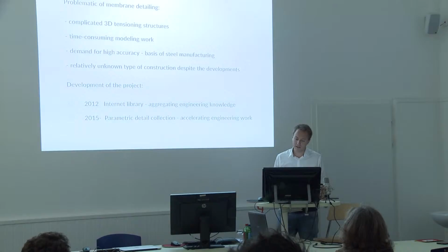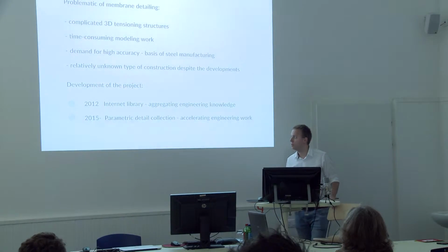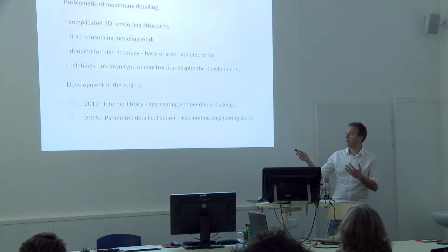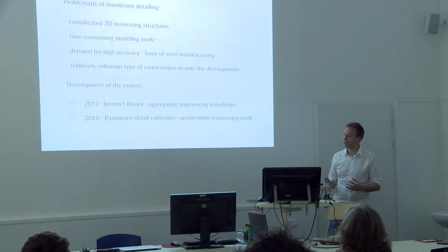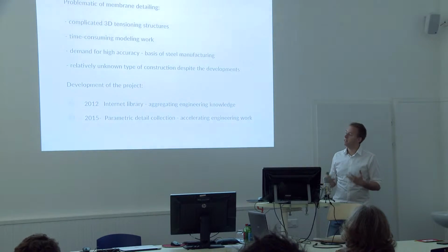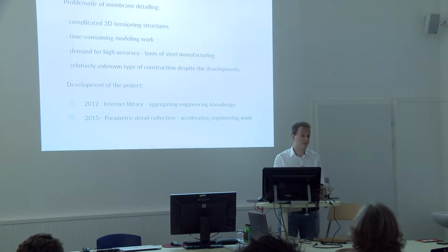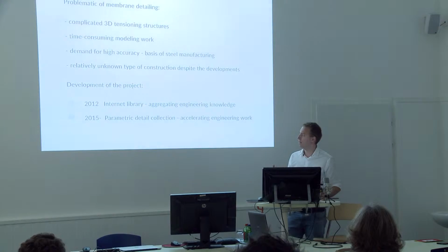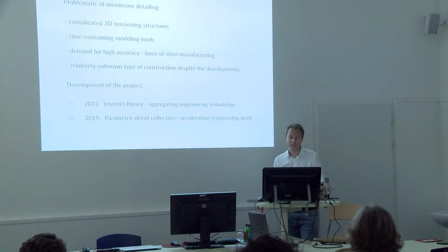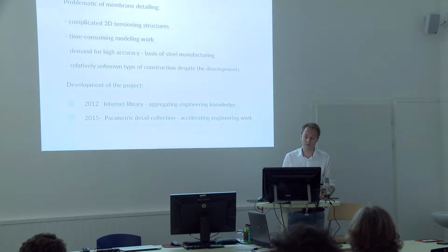actually this is why this project has two goals. The first goal, even at the start, was to create a compilation of this knowledge. The details of the membranes are very strongly related to the stability of the structure, because these are the weakest points of the surface where you have the tensioning elements. On the other hand, the degree of freedom of the elements is very important for the entire stability of the structure, so that the surface is not folding when you build in some wrong detail.